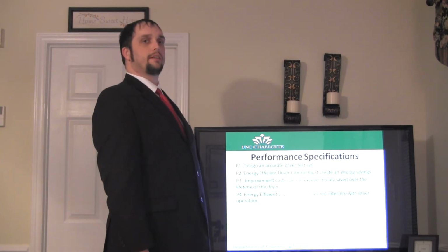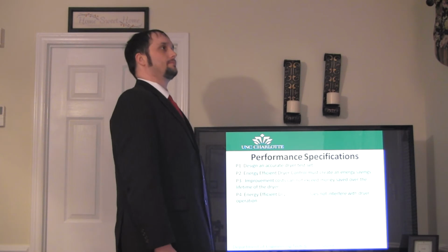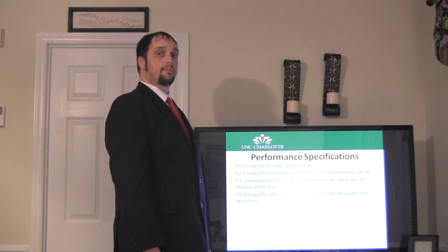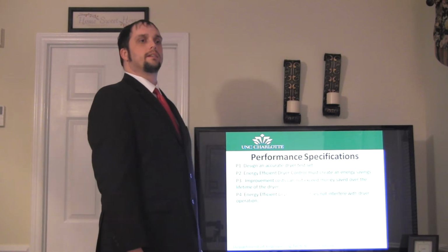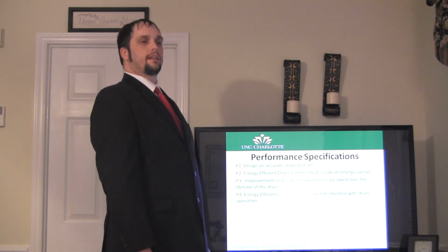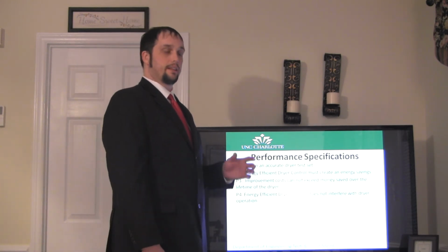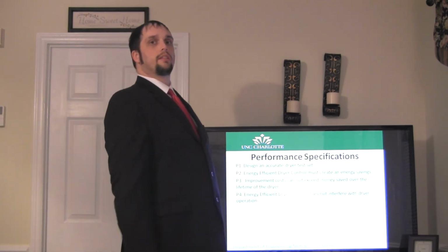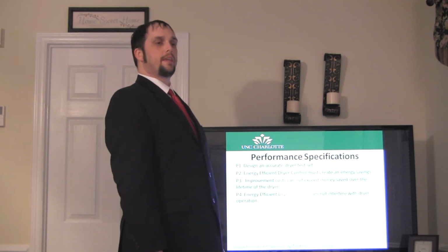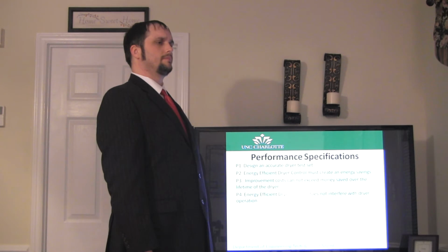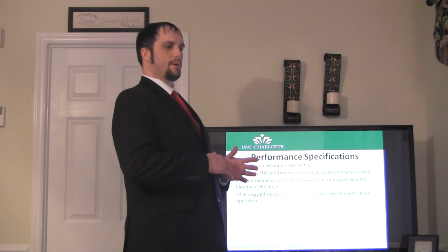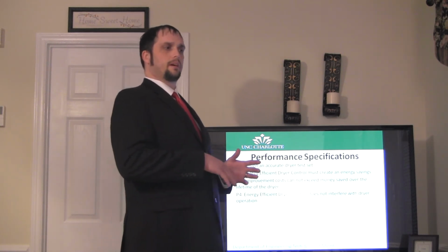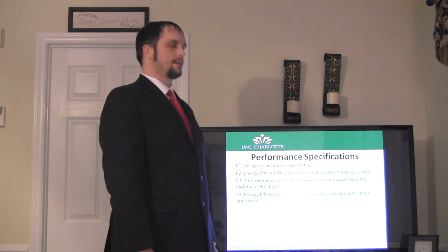We calibrated the current by taking a current transformer and an ammeter and running through a range from 0 to 30 at 5 amp increments, and saw if there was a linear correlation between the known ammeter and also the current transformer used in the test set, and then simply interpolated the ammeter data and made a best fit for the current transformer that's in the test set.